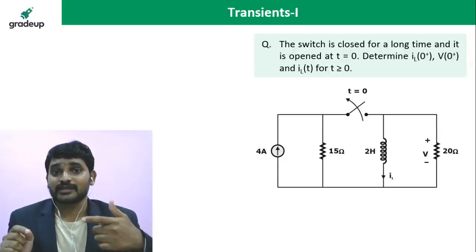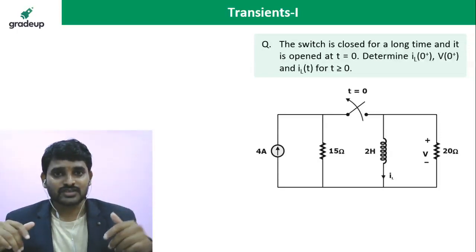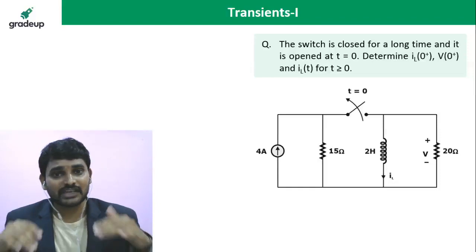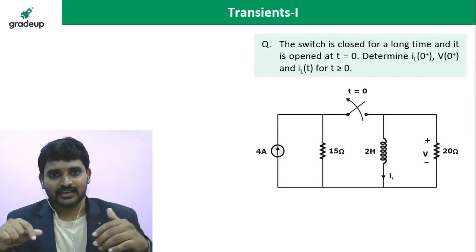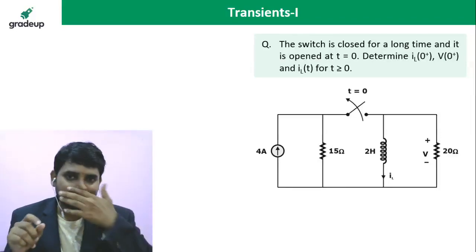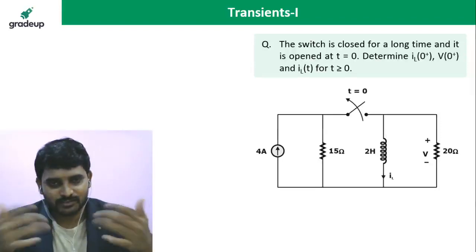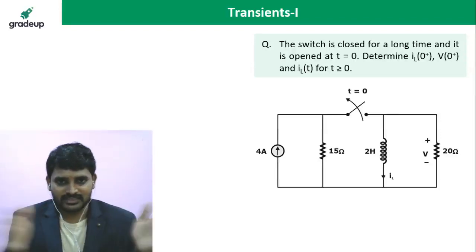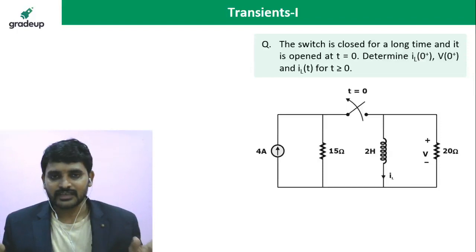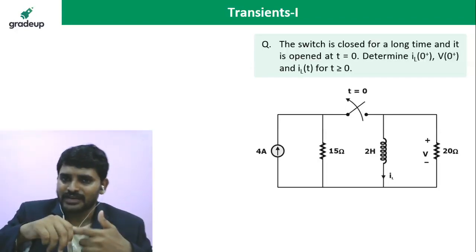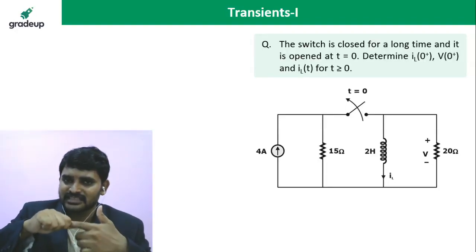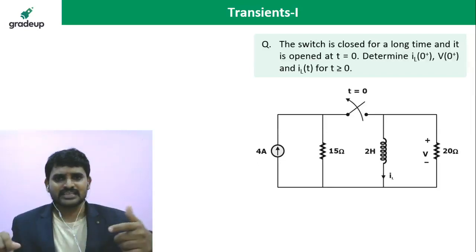Why? Because body resistance is more, so the discharging time is very quick. Tau is equal to RC. R is more, so the discharging time period depends on body resistance and capacitor value. So you might experience the rush of electrons for 1 or 2 seconds, and after that nothing.